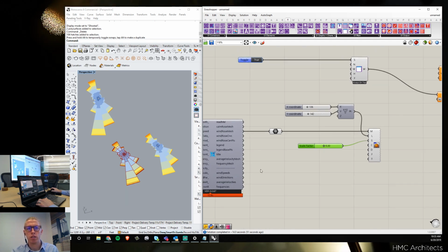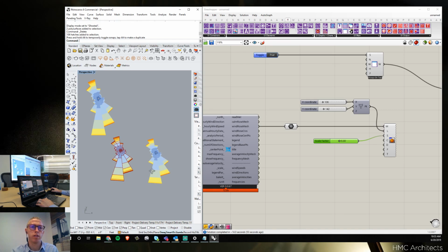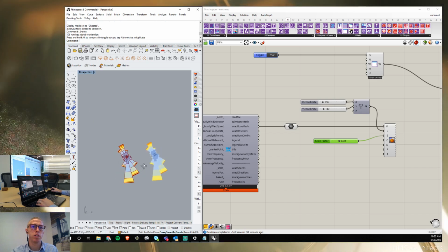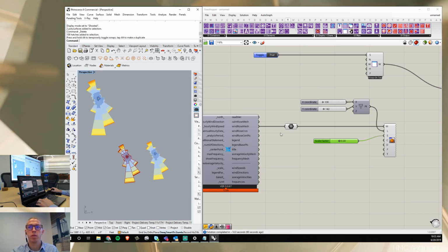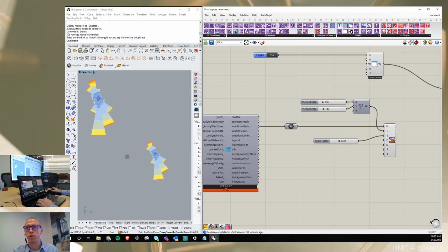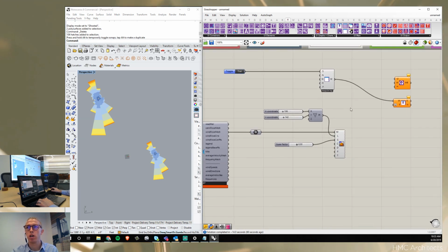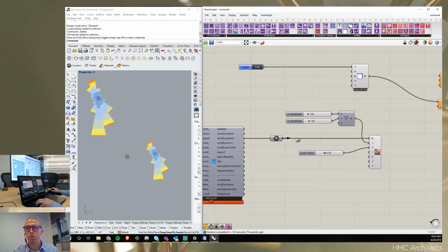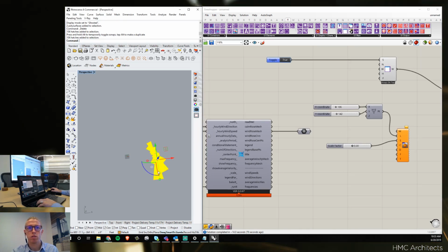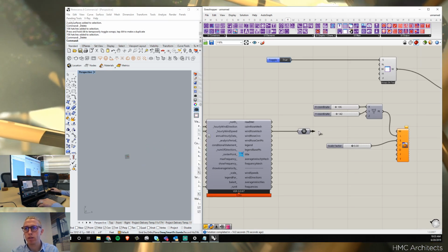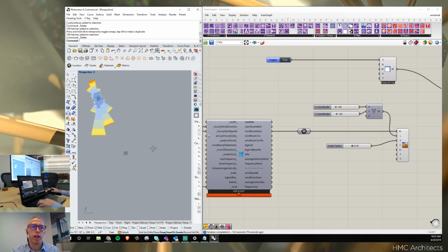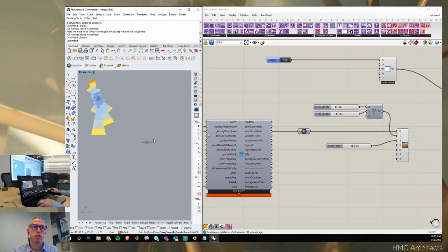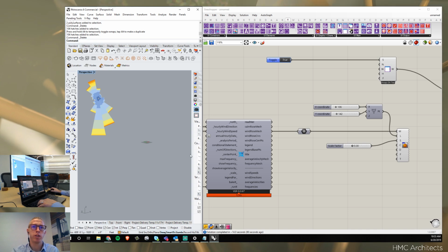So the nice thing about this is if we are modeling a building, sometimes we might not want that to be rendered in the actual environment. So if we come here, we can preview these things or toggle these things off. That is the hatch we baked. So now it just appears as if that graphic is a part of my user interface.